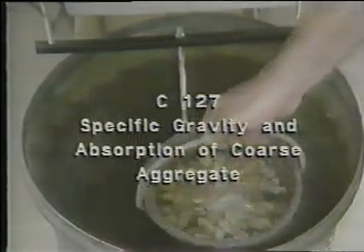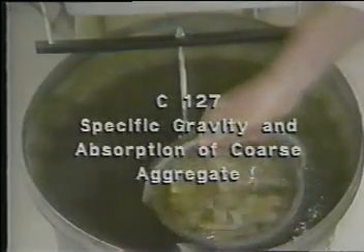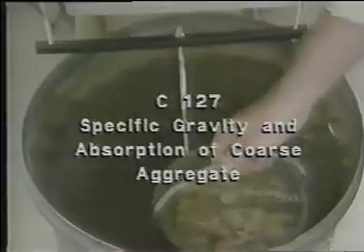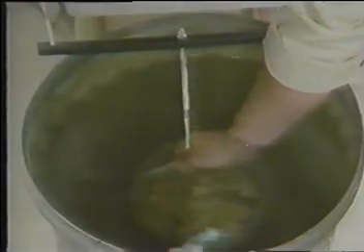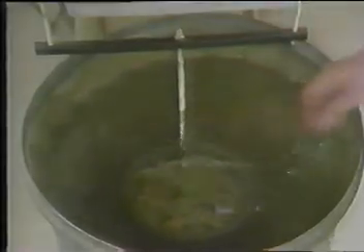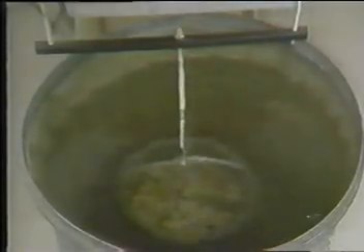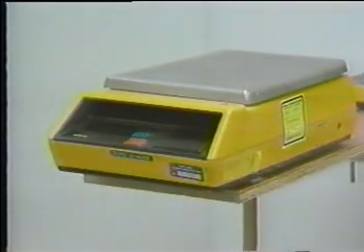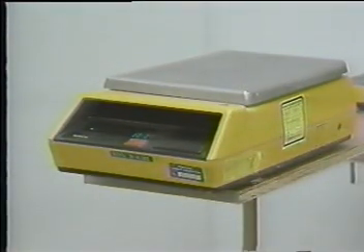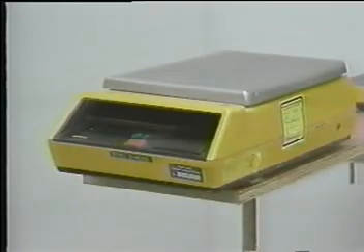ASTM C127, Standard Test Method for Specific Gravity and Absorption of Coarse Aggregate. This method covers the determination of specific gravity and absorption of coarse aggregate. Since bulk specific gravity and absorption are the values commonly used in concrete mix design, we will confine this demonstration to those items. Equipment needed for this test includes a scale or balance readable and accurate to 0.05% of the